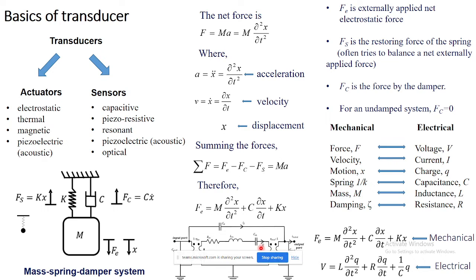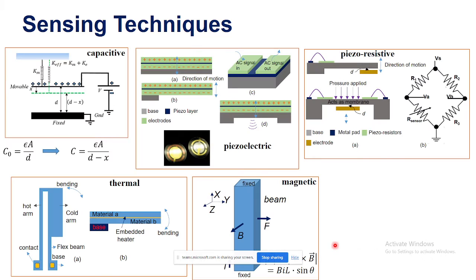What is the output of the mechanical circuit here? It is the velocity, because it's in motion. So that velocity can be converted back to the electrical domain by using another transducer model. So here is the transformer that is modeling the energy conversion again, back from the mechanical domain to the electrical domain. So the output will be the current, and that is how we can understand the mapping between the mechanical domain and the electrical domain to understand the behavior of a transducer.